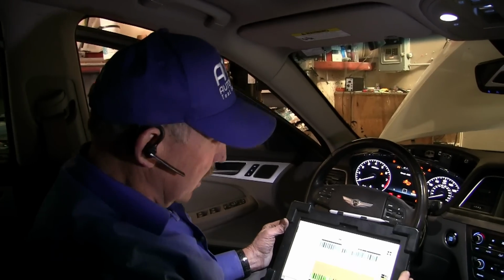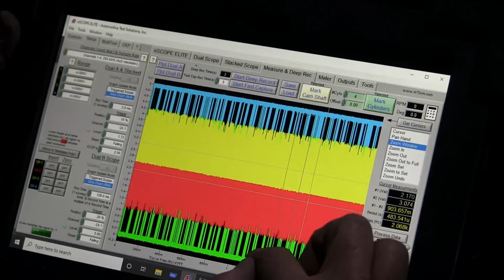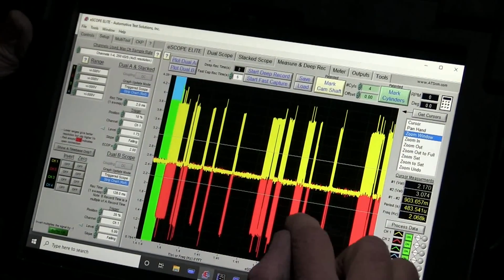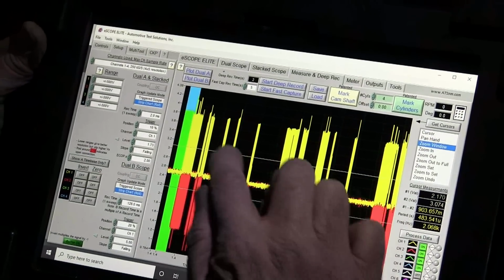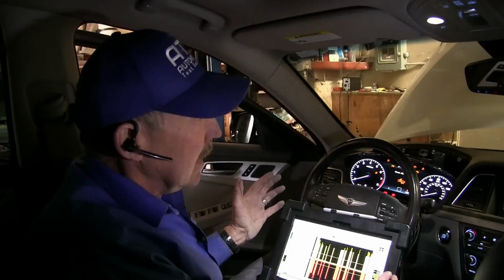control module. So now we can see that we have a good bus. If we come in here and look at the bus, it's fine. These are my data packs. We're making good data, so that's not the problem. So the way that this works is the bus is up and functional now. The problem is the parking brake module, and that's going to have to be replaced.